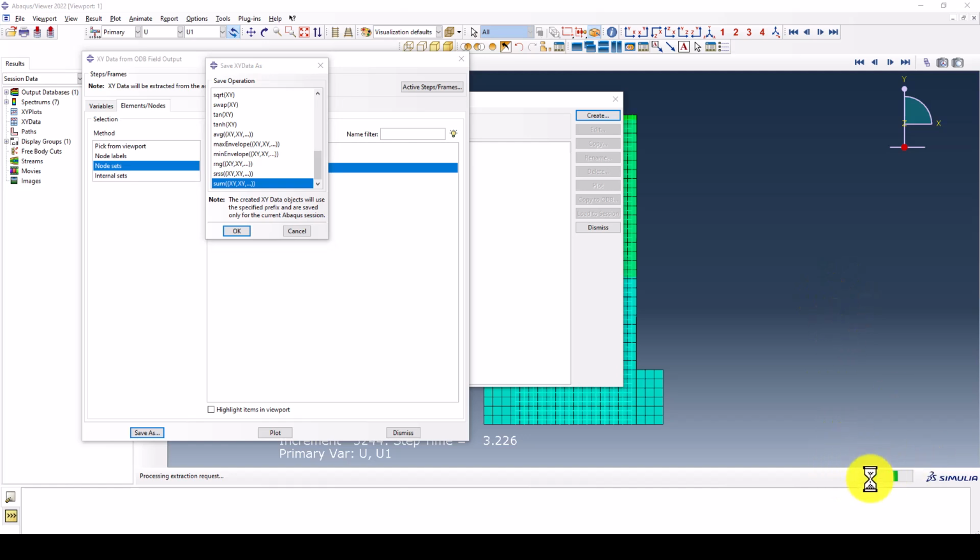The 3,000 points is quite large, and with a lot of nodes it takes some time. And now it takes 7%. So in the time history output, you should use output based on time, like 0.01 second, so that 10 seconds will be about 1,000 points. We don't need too many points, and this causes a lot of problems or issues during the analysis.